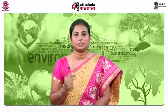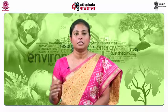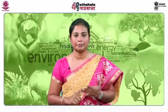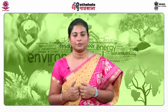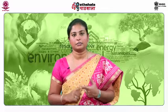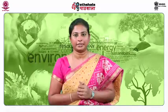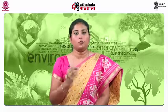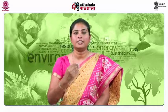An ideal gas collection system consists of a sequence of gas collection wells which are positioned throughout the landfill. The gas collection wells are designed based on the volume and density of waste and the depth and area of the landfill. Collection wells offer pathways for the passage of gas. The gas collection system is very important because if it does not work properly, an explosion can occur within the bioreactor. You can also see more gas generation in the early phase of operation. Moreover, compared to conventional landfills, landfill bioreactors generate a high amount of gas.